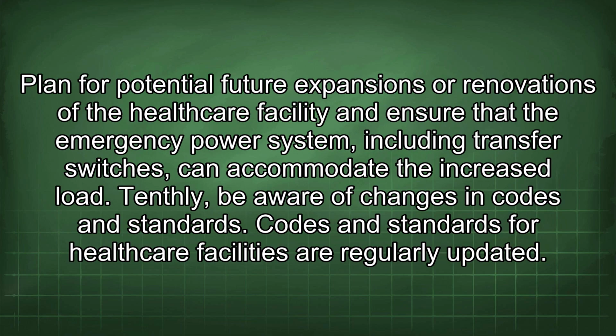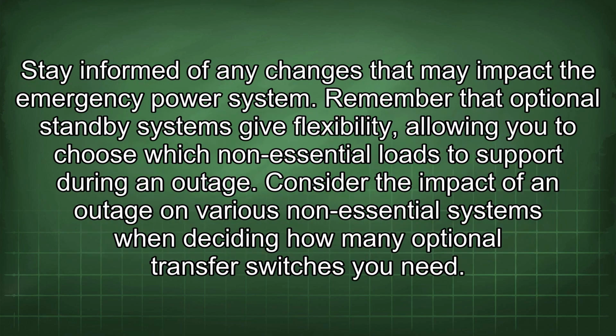Ninthly, consider the impact of future expansions or renovations. Plan for potential future expansions or renovations of the healthcare facility and ensure that the emergency power system, including transfer switches, can accommodate the increased load. Tenthly, be aware of changes in codes and standards. Codes and standards for healthcare facilities are regularly updated. Stay informed of any changes that may impact the emergency power system.